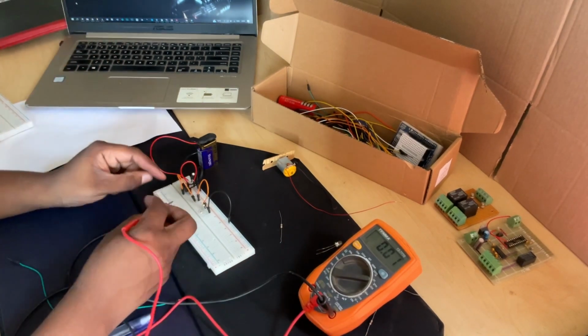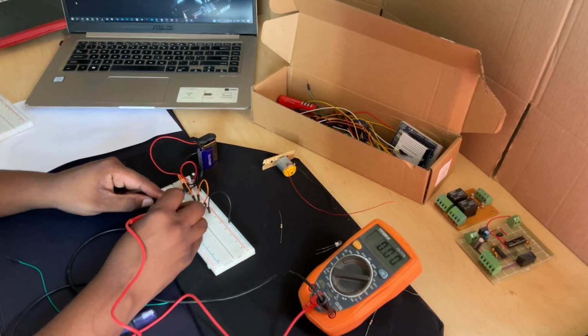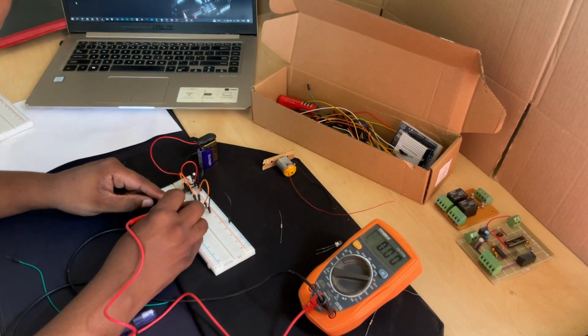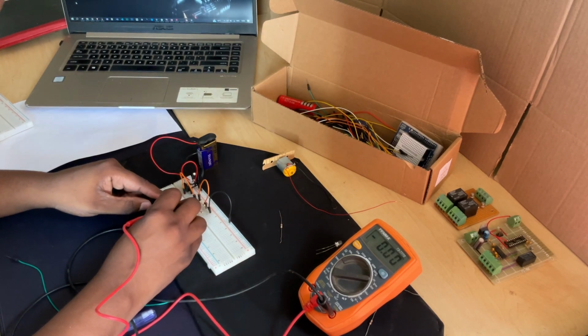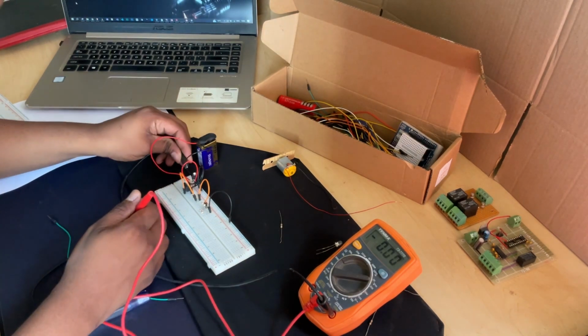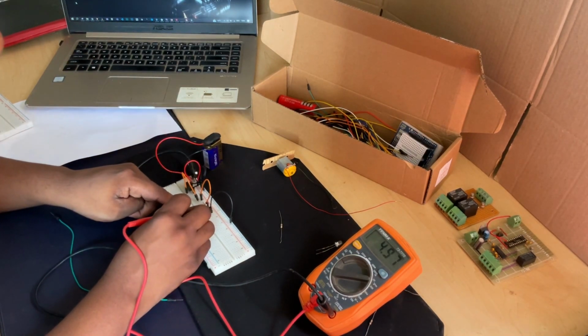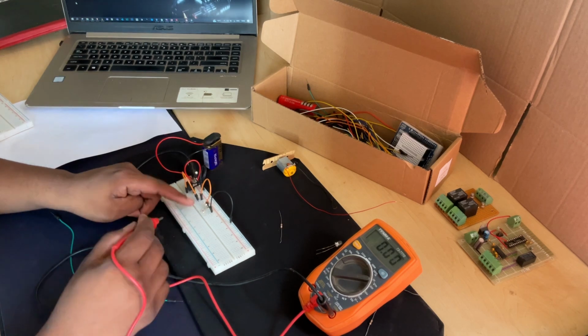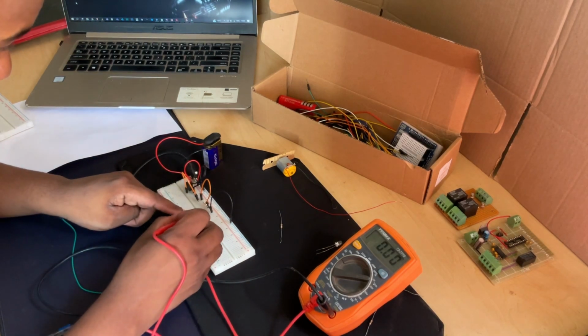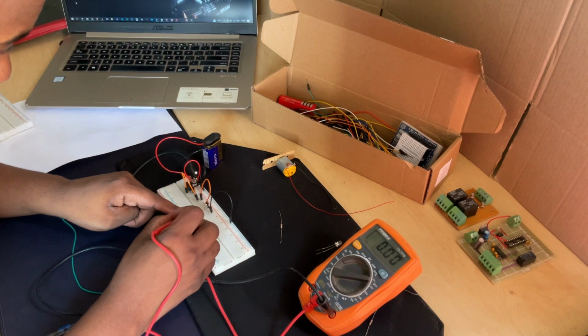Over here an honest mistake has been made. I forgot to connect the negative lead of the multimeter to the circuit, and there I'm rectifying the mistake now. Then we'll start seeing our value. As expected, the input voltage is around 5 volts at 4.97. So measuring across each of the resistors will still give us the same voltage.